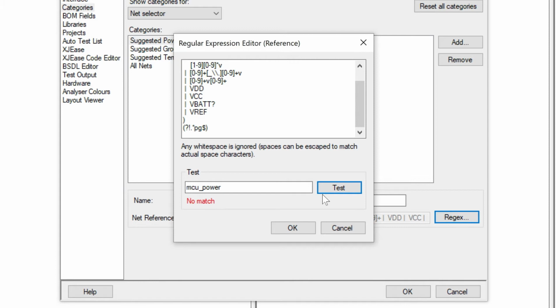So what to do? Simply click in the box and you'll be able to alter the expression. You can either change what's already there or insert an additional item. Add the pipe symbol for an OR and follow it with something that matches your names.